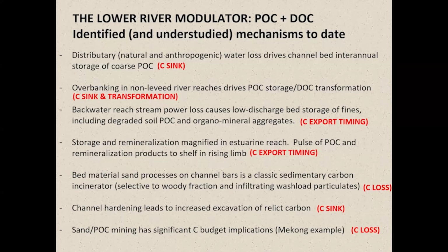Backwater reach stream power loss causes low discharge bed storage of fines, including degraded soil POC and organic mineral aggregates. We showed there's this dramatic deposition of material in the backwater reach during low discharge periods, and then that material is remobilized during high discharge.